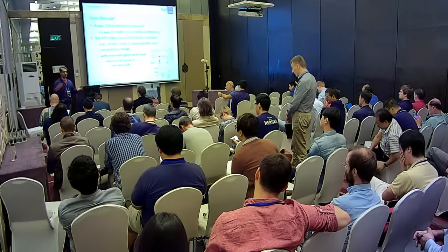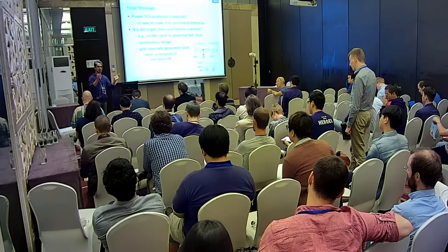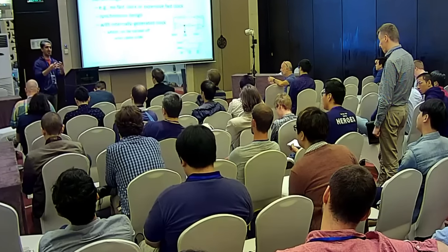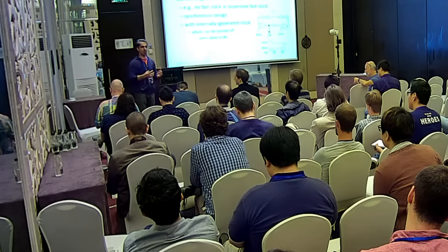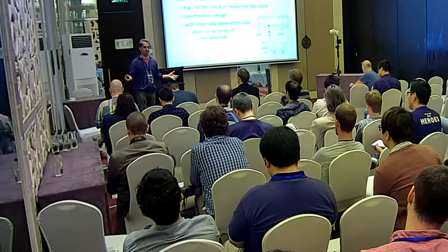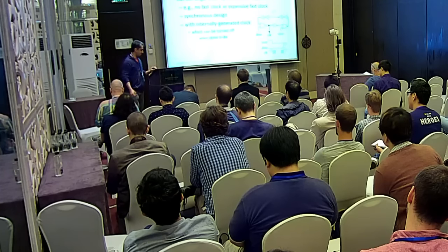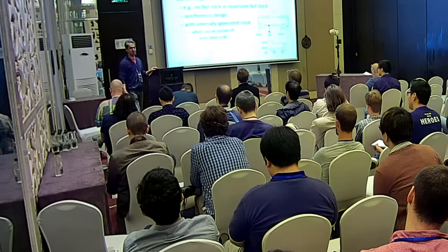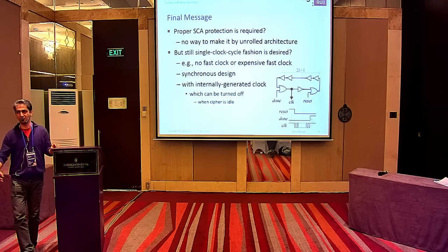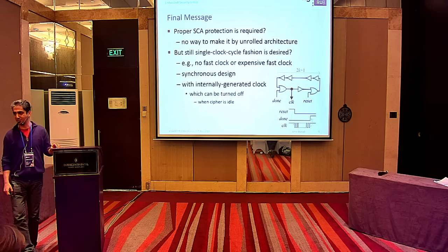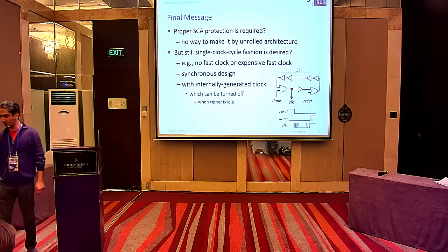The problem is that in the fully unrolled design, many gates are combined into the cells that are available in the library. And then just by trial and check, you can check how big this design is or what the latency of this design is. I would say it's not contradicting the main goal of having a low latency cipher if you go for a round-based architecture. Of course, what makes sense and is important is to have a very low number of rounds, which you can see also in Prince. Prince has a pretty low number of rounds compared to other ciphers which have 4-bit S-boxes.